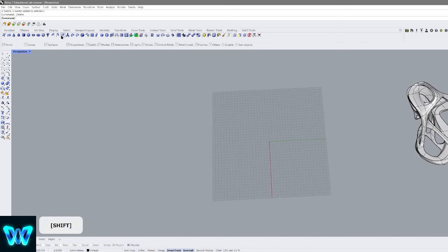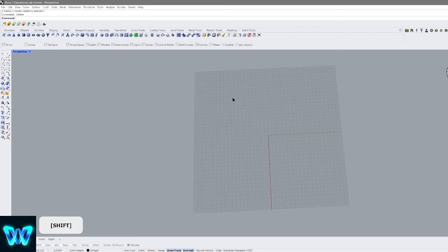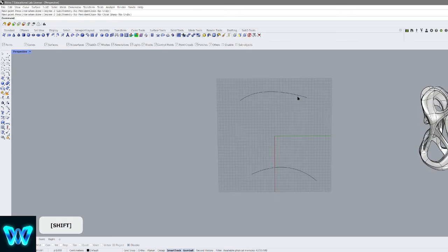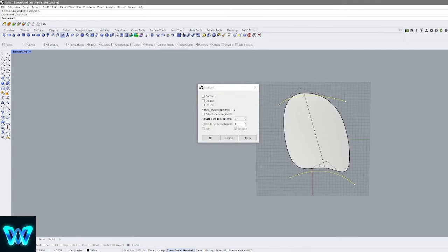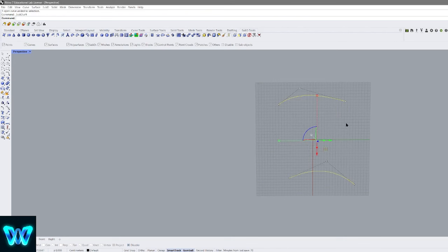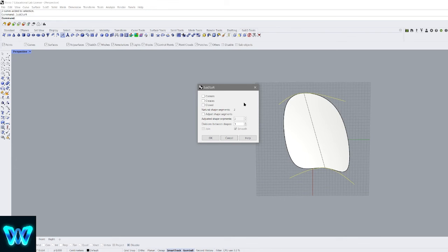Now going into the third, it's called SubD Loft. And SubD Loft is very simple. All you have to do is you need two curves, open or closed, doesn't matter. And then all you have to do is select both and then SubD Loft. And what it will do is create a connection between these two and a form around it. So we can add corners, we can add creases. I will go over what creasing is. Closed and open, and it only works when it's 3D. And you can adjust the segments too, in order to create more detail. And at the same time, if you make it SubD friendly, and then you loft it, you see that it follows the curvature perfectly.